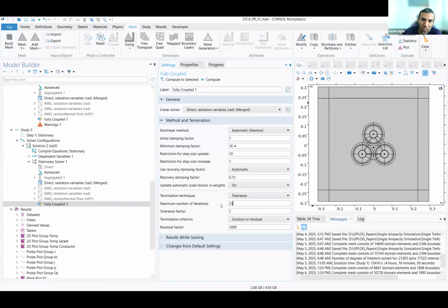If during the simulation the tolerance and convergence criteria are satisfied, then it'll keep computing, and go to the next iteration, in this case the next time step probably. Well, this is stationary, there's no time step. If it's time dependent, you have a time step and iteration. Stationary is just iteration, right?